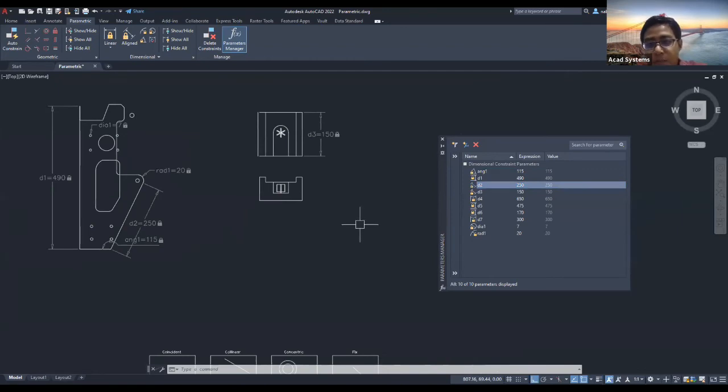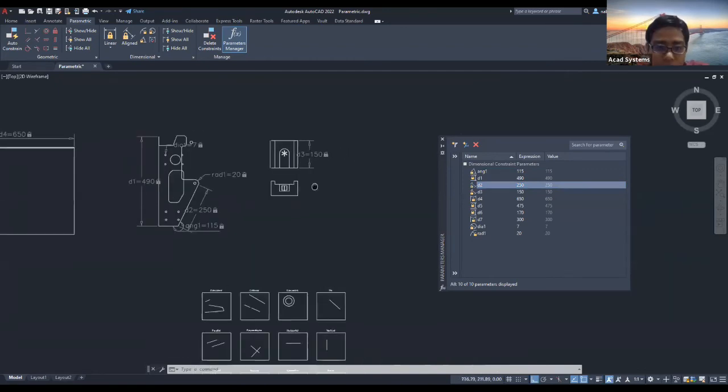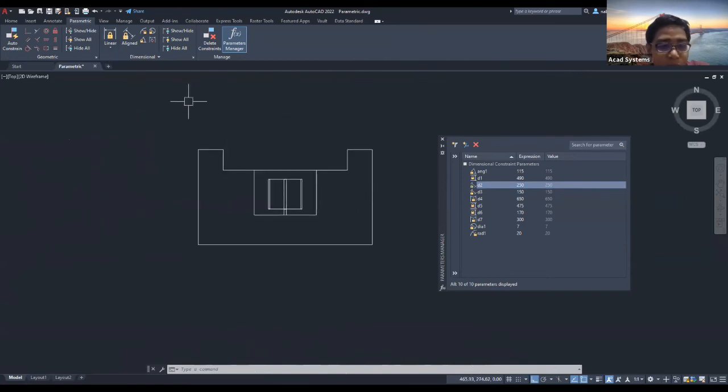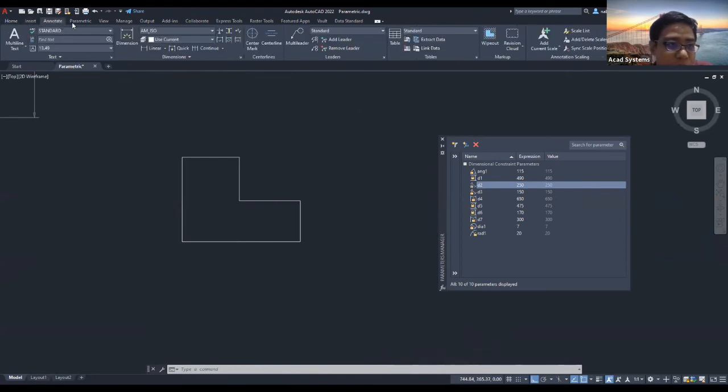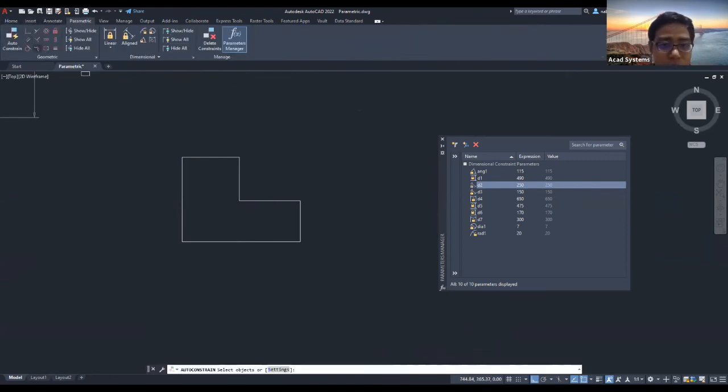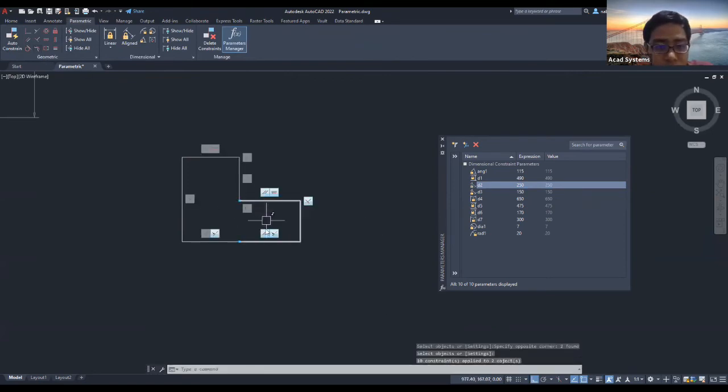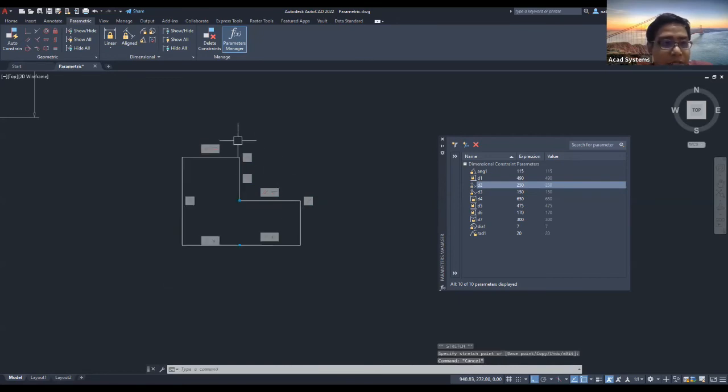Is that you can also create some parametric rules. For example, let's take a look at some example from here. Or let me just make some simple drawings so you can see much more clearly. Right, so I'm going to apply some of the other tools from here, some other constraints from here. So go to metric. So let's say auto constraints. So also this has been constrained. Right. So the last thing that has not yet been constrained is the dimensional constraints.